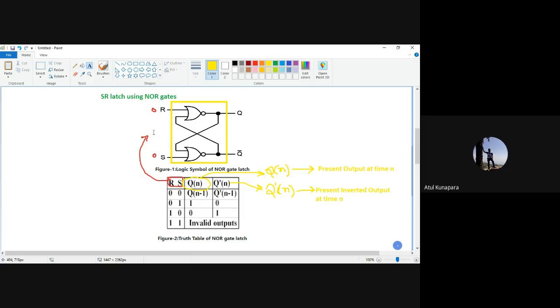When we say to give the input, when I say I'm giving 1 here and 0 here, what does that mean? When you are giving 1, that means you are connecting some positive voltage at this circuit, which has another point grounded. And when I say I'm giving 0 volt here, it is directly connected to ground. This is how your wiring is going to be done.